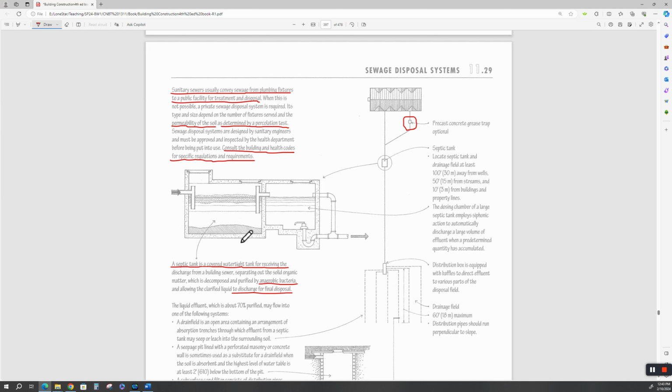Once that sludge is fully digested, it has to be dewatered either through centrifuges or a belt press, and then that sludge can be put in a sanitary landfill. They used to let them use it to fertilize hay fields, but I don't know if the health department allows them to do that anymore.